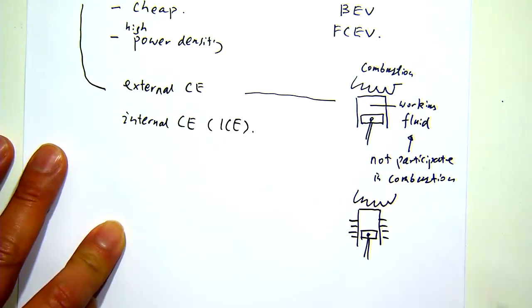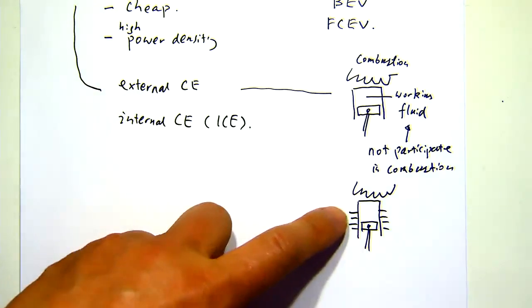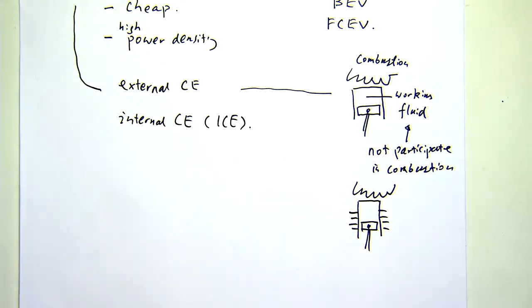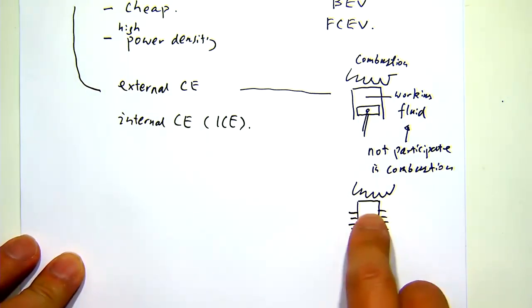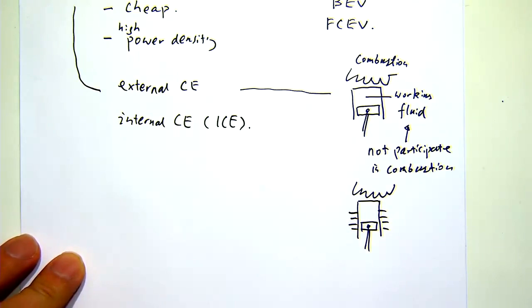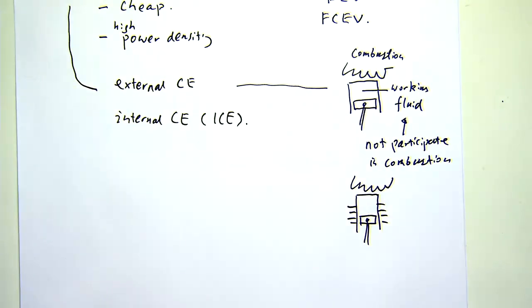you can see there is quite a bit of fin-type structure here, right? That is to enhance the heat transfer. When the gas gets there, because of the fin structure, it loses heat. The temperature goes down, and when the temperature goes down, the pressure goes down. Then with lower pressure, the piston will move from this side back to that side. When it reaches the other side, it's hot and is pushed again. So this back and forth process drives this Stirling engine.